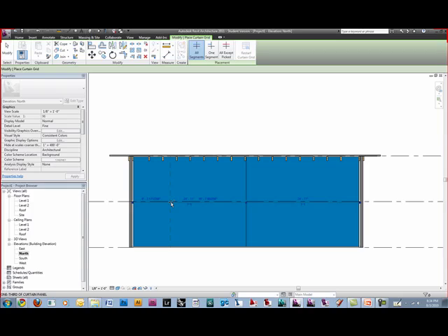If you just slowly move across, it'll snap to 1/3. See? You'll notice it snaps because it kind of jumps. It's not going to tell you, hey, you're at 1/3, hey, you're at 2/3. It's not going to give you an emblem. The universal emblem for midpoint is a triangle in Revit, but it's not going to do that. It'll just stop, and you'll get used to it.